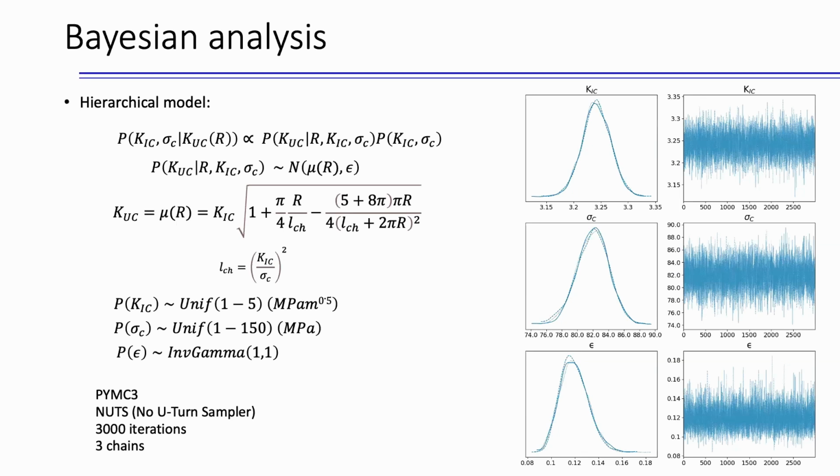It is an experimental error. Also, we are supposing, and probably this hypothesis is stronger, that the standard deviation is the same for all the radii. This is the stronger hypothesis. In this first calculation, we suppose the theory of critical distances, maximum stress. In the first plot, we can see that the uncertainty we are obtaining is not very high. So at the beginning, we can think that this procedure is correct, or is not very bad, to determine the material toughness from U-notches.